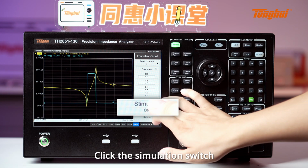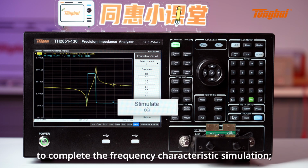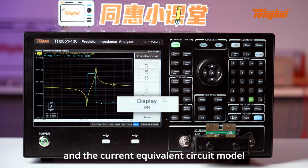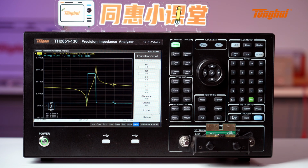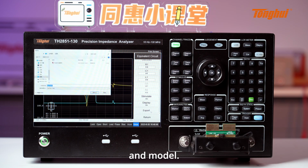Click the Simulation switch to switch it on to complete the frequency characteristic simulation. Click the Display switch, switch it on, and the current equivalent circuit model and equivalent circuit parameter values are displayed in the lower left corner. Click Export Result to export the equivalent circuit parameters and model.